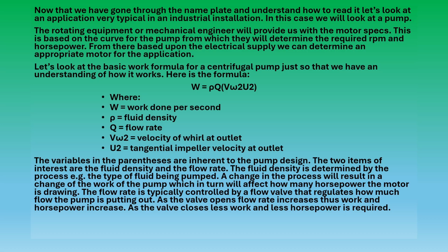The two items that are of interest to us are the fluid density and the flow rate. The fluid density is determined by the process, for example, the type of fluid being pumped. A change in the process will result in a change of the work of the pump, which in turn will affect how many horsepower the motor is drawing. The flow rate is typically controlled by a flow valve that regulates how much flow the pump is putting out. As the valve opens, flow increases, thus work and horsepower increase. As the valve closes, less work and less horsepower is required.